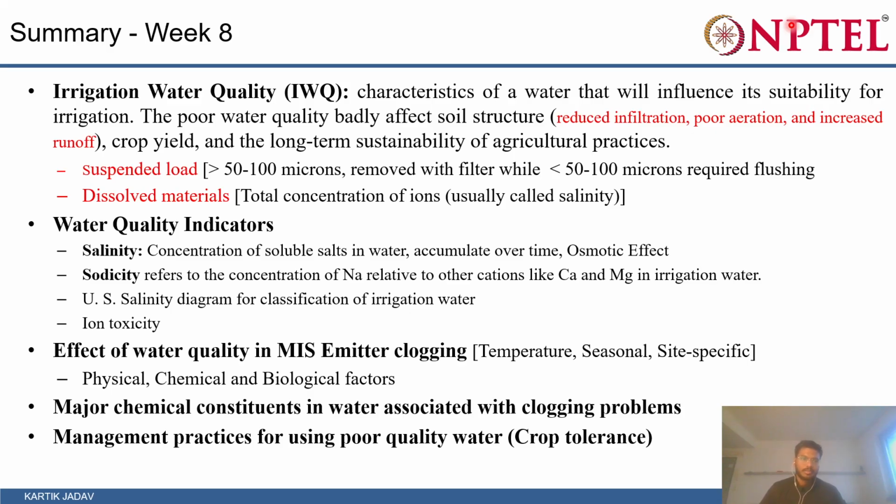There are in general suspended load and dissolved material. If the suspended load size is greater than 50 to 100 microns, it is generally called suspended load, and it is generally removed by a filter. While for a smaller suspended load, less than 50 to 100 microns, it requires flushing. And then we have dissolved material, which is the total concentration of ions, usually called salinity. So this is the fundamental aspect.